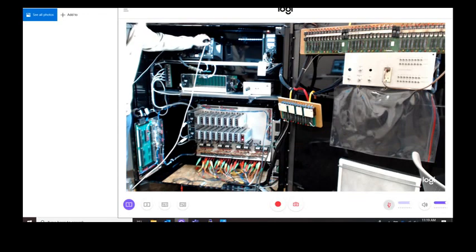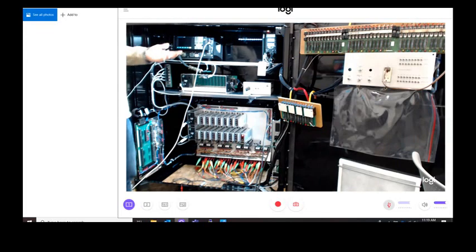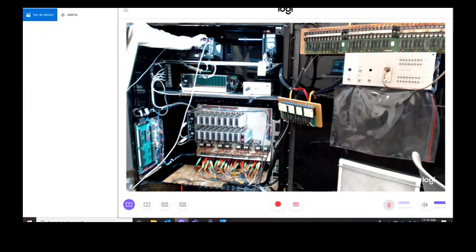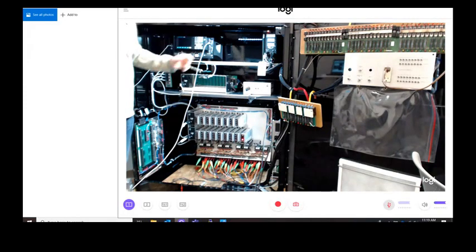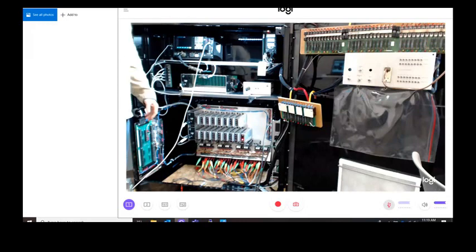This port right here basically is a heartbeat pulse of the processor board. It doesn't have anything to do technically with these ports and how they work. It's basically just telling us that the processor board is working. So always disregard that one. It's just basically when the controller is powered up, that's on. It doesn't mean anything more than that. So try not to confuse that with our port transmit and receive lights.